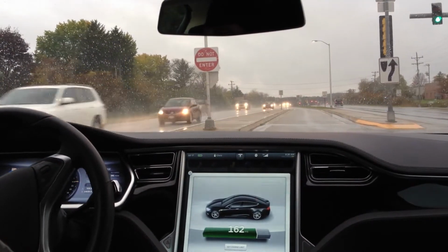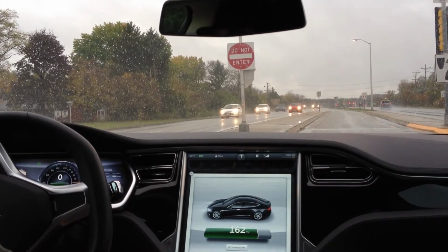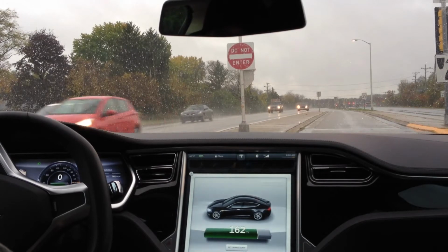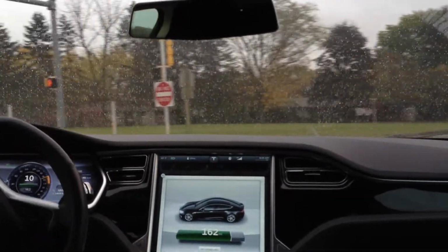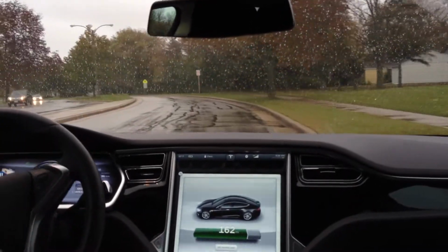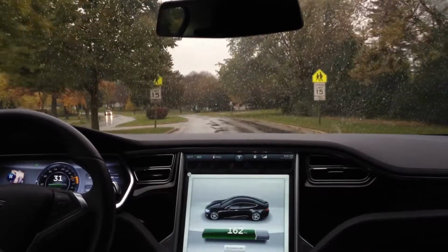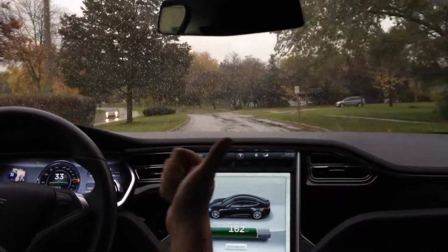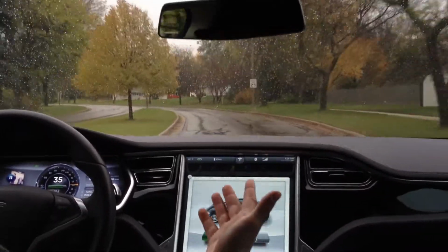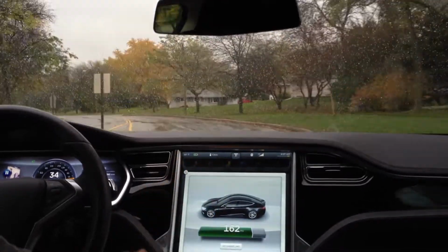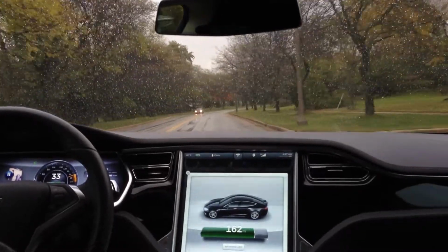So that means you're being billed 10 kilowatt hours for every hour that you are charging a Model S at 40 amps on a 250 volt circuit. To find the cost of that, you take those 10 kilowatts times how much you're billed. In my case, 5 cents per kilowatt hour, which would come to 5, 10, 15, 20, 25, 30, 35, 40, 45, 50. I hope you got your fingers out so you can count with me. So that was 50 cents per hour to charge the car at full charging speed.